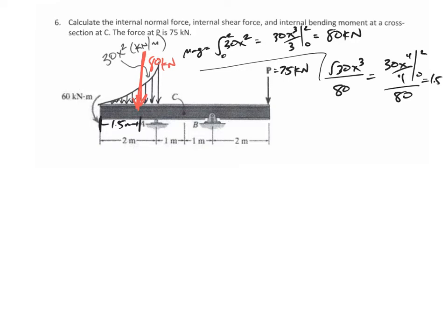All right. Before I cut this open, I want to find the reactions. Whether I'm looking at the left or the right, probably need to find some of those reactions. I think I'm just going to go ahead and find both of them. Sometimes you don't have to find all the reactions. Sometimes you can take some shortcuts. But here, there's going to be an AY, and here at B, there could be a BY, there could be a BX. So looking at the whole free body diagram,